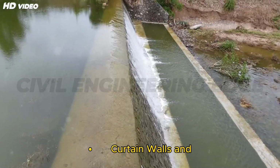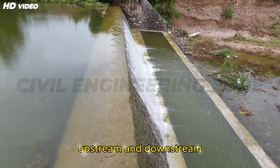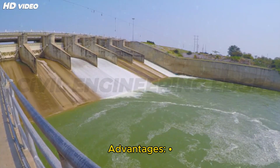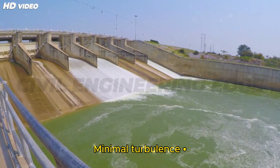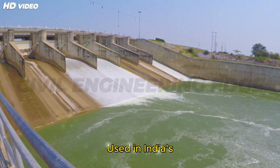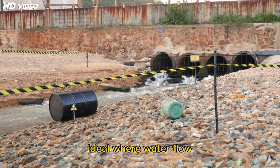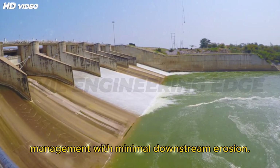Curtain walls and protection works. Curtain walls are provided both upstream and downstream for seepage control. Riprap and stone pitching are used for protection. Advantages: superior energy dissipation, minimal turbulence, ideal for large irrigation channels. Used in India's Rajasthan and Madhya Pradesh projects, the straight glacis fall is ideal where water flow is high and needs efficient energy management with minimal downstream erosion.